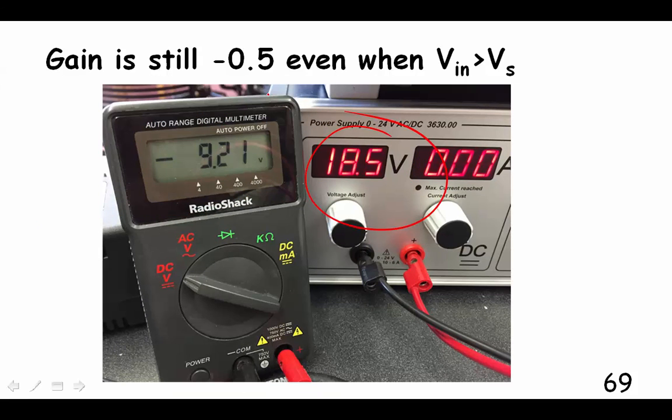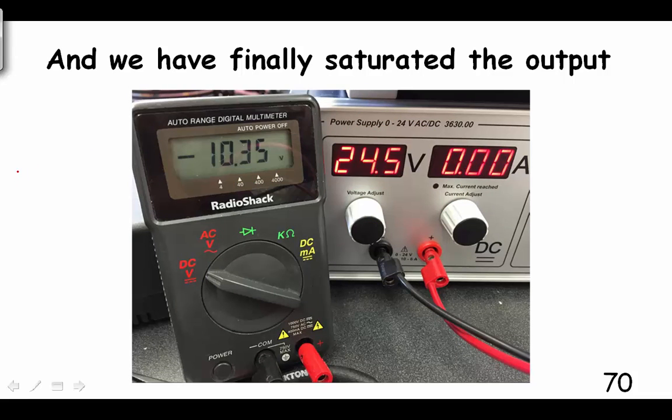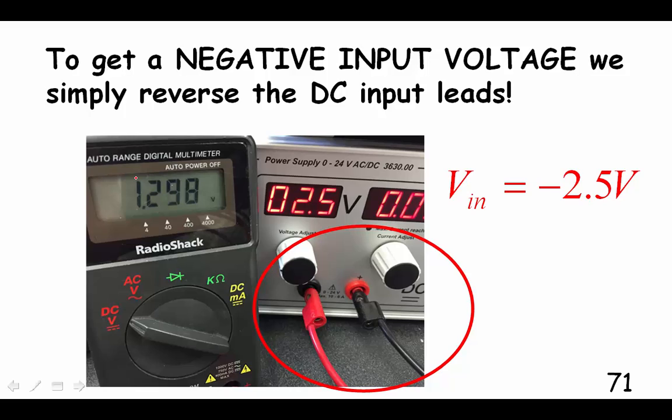So here we have an input of 18.5. Again, we have a gain of -0.5. So we take half of that, and that's about right. We got the negative sign. And finally, we're asking the op amp to give us 12.25 volts, but it can't because it's saturated. So there it is, saturated at its supply voltage.